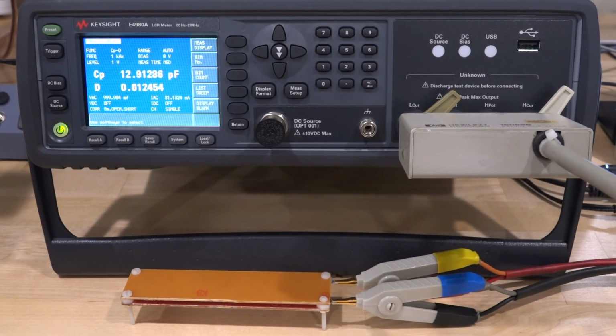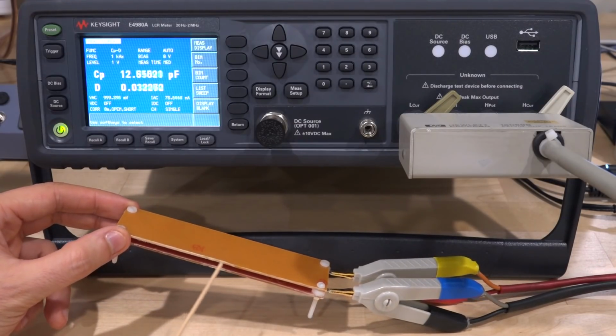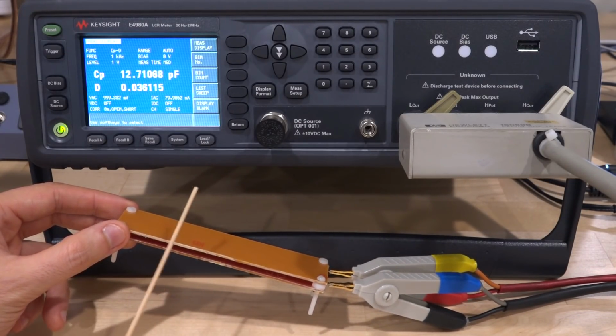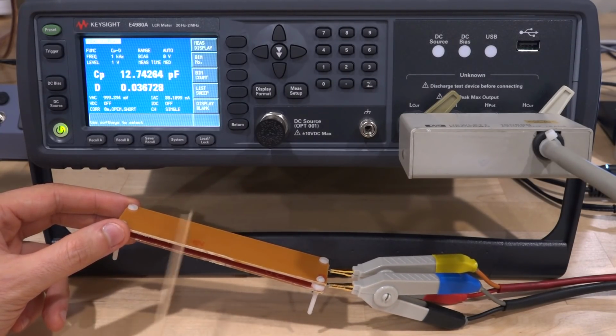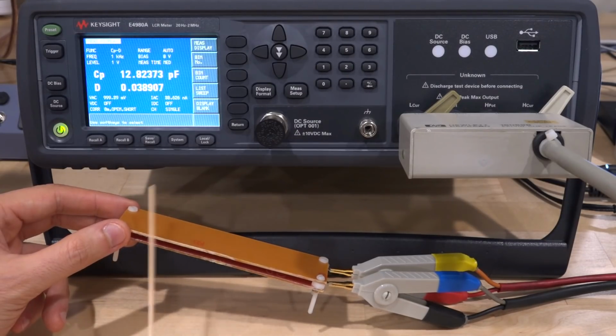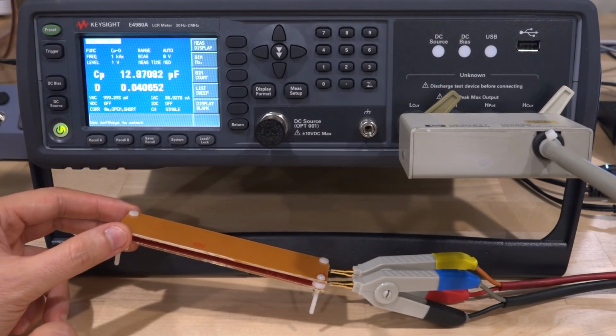So it's not exactly 10. So why is that? Well, that's because we're making the most simplistic assumption about the nature of this capacitor. We are ignoring the fact that there is plastic on the corners. We're ignoring the fact that there is tape on there, which has a different dielectric constant than air. But more importantly, we're assuming the electric field is fully confined between the two plates. And it's not, because there is some fringing around this capacitor too. And that fringing field not only increases the capacitance because that's outside of the area we calculated, but it also goes through the dielectric material of the PCB too, which itself is about 4 or 3.5 or so. So that also changes everything. That's why we get a little bit more capacitance.